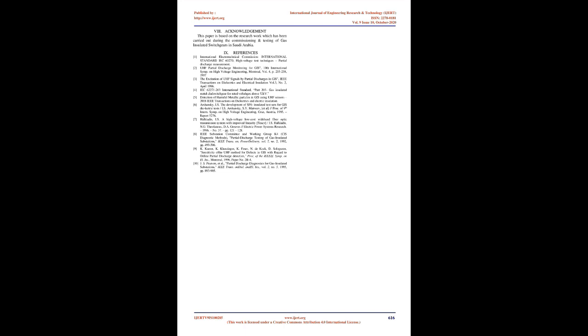C. GPS system. A global positioning system interface module is installed in the control cabinet, which translates the signal of the GPS system to a time code signal via serial link to the server. The time signal is supplied from the GPS module. Data is received by the GPS module via an external antenna. The antenna cable to the cabinet equipment is protected by a surge voltage protector.